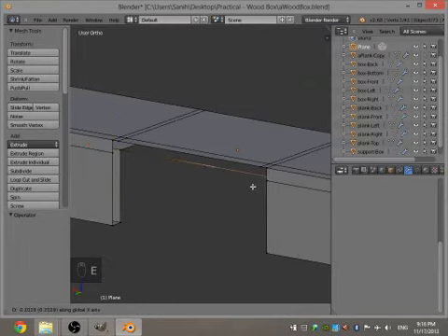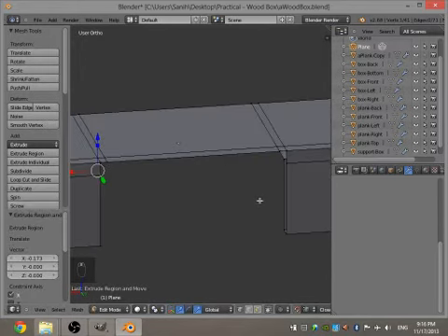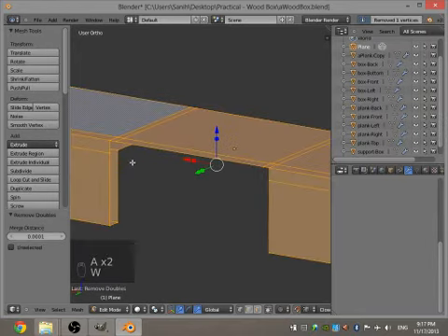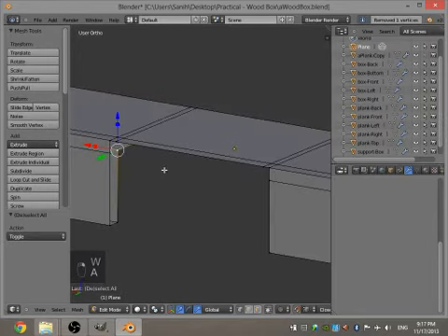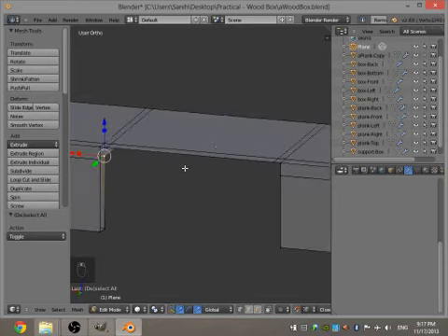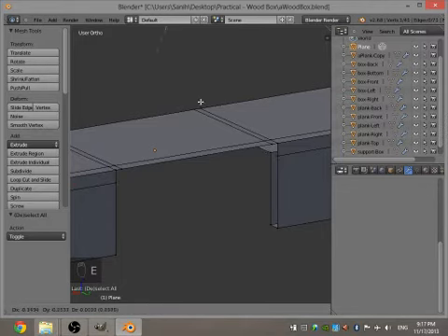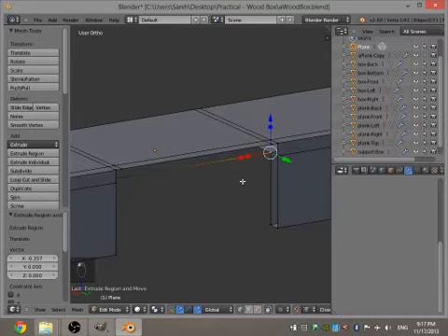And I can actually turn it around, right? Okay, this is going to be a bit more complex. Grab the vertex that you want, turn the view around to the one that you want to connect to. Then you press E, right? Now you have the thing grabbed, right? And then you get it close to the one that you want to grab to, and it snaps to it automatically, right? And then let go.